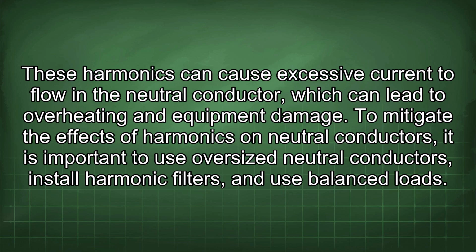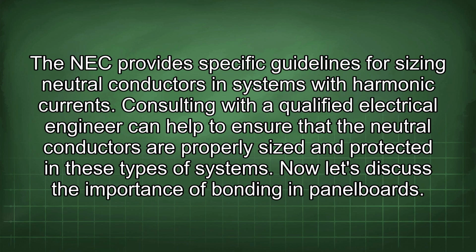To mitigate the effects of harmonics on neutral conductors, it is important to use oversized neutral conductors, install harmonic filters, and use balanced loads. The NEC provides specific guidelines for sizing neutral conductors in systems with harmonic currents. Consulting with a qualified electrical engineer can help to ensure that the neutral conductors are properly sized and protected in these types of systems.